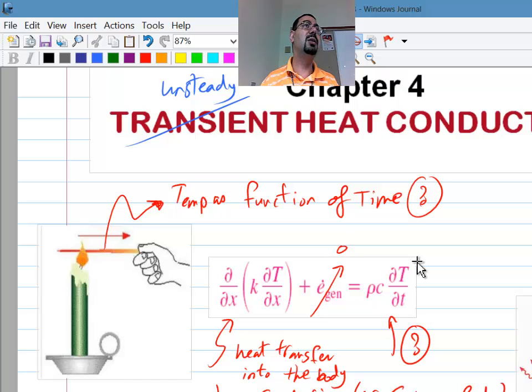Now I would like another way to get rid of one of those variables, x and time. You can get rid of the x domain by treating the whole mass as the same temperature. Excellent. You're not looking at the temperature at each individual component, just the whole thing is one temperature. Devin is saying, why don't we treat the whole thing as just one x? There is no temperature distribution inside. It's not like one part of the water is hotter than the other. The whole water is sitting, it boiled together, it cooled together.